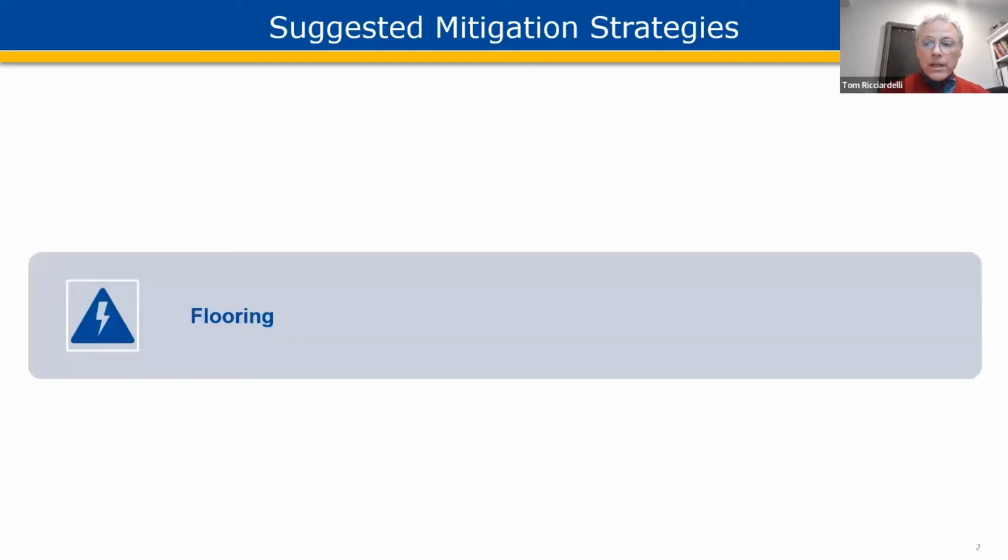The first one is flooring. In a manufacturing environment, you'd require a fairly controlled flooring material that would have essentially an electrical connection between the person and the floor to ensure the lowest levels of static buildup on a person. In this case, that's not necessarily the requirement. We're really trying to limit charge buildup to under a few thousand volts, and in electronics manufacturing, you want to limit it to below 100 volts. So it's a very different phenomenon.